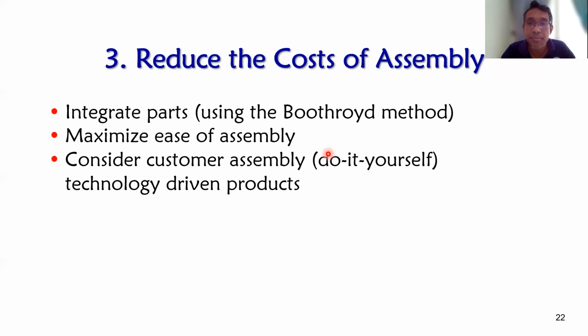Okay. So number one, integrated parts do not have to be assembled. As you learned inside the product architecture, when two chunks are combined together, we can get an integrated part in the design, with no need to assemble. So the assembly effect is built into the geometric features of the part.